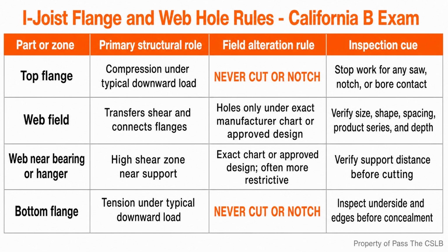The same discipline applies after a defect is found. An unauthorized opening is not repaired by instinct. I do not assume that a plywood scab, a short sister, blocking, screws, or a metal strap restores the original capacity. Some manufacturers publish repair details for specific damage. Other conditions require an engineered design. I preserve the product information, photograph the damage, stop concealment in that area, and obtain the controlling repair direction.